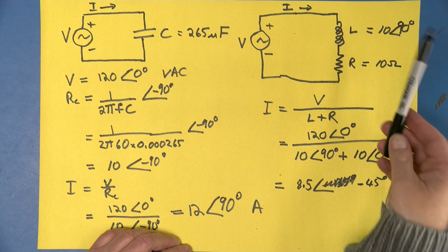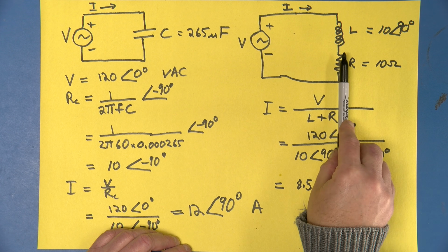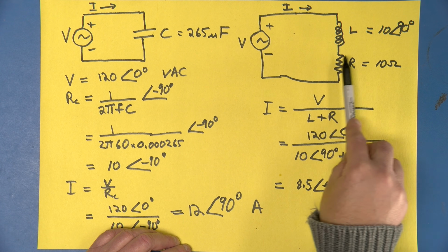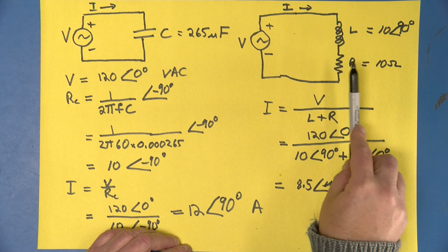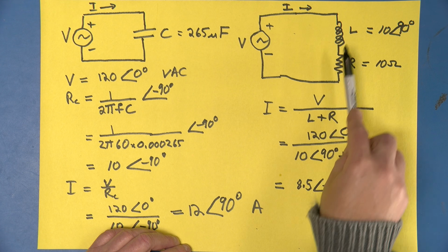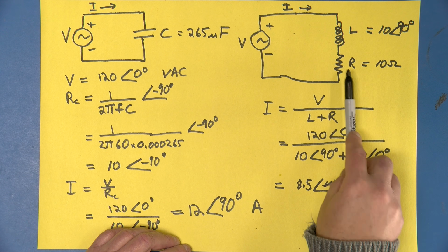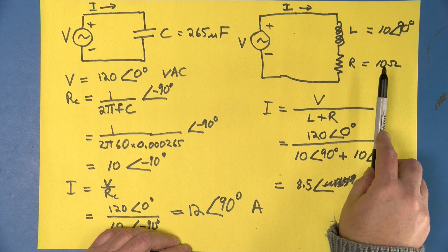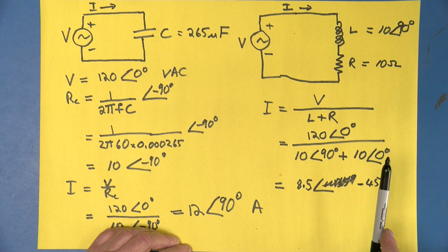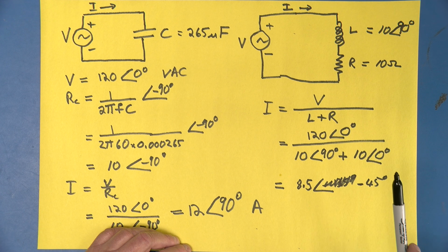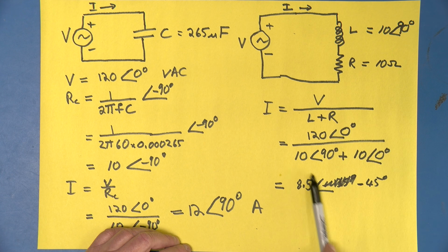Well, it's because the voltages across these two things, which are at phase angles to each other, don't add up as the simple sum of the two voltages. They actually end up being as if they were sides of a right triangle, with the sum being the hypotenuse. And if you remember the Pythagorean theorem, you can figure out how big that is.